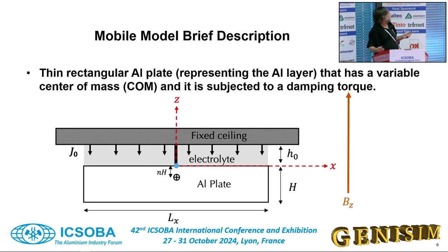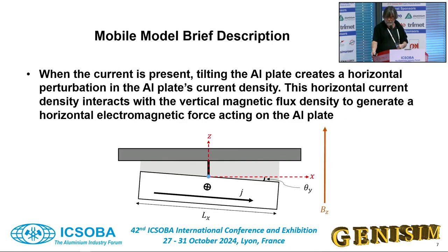If the current density is enough, depending on the ACD and the metal pad and the magnetic field, it will amplify or decay. So you kick it, you get an angle. It's a thick plate, so it can only oscillate in what we call a 1-0 mode or a 0-1 mode in the other direction. Those are the only two modes allowed, because it's a rigid structure. But if you kick in one direction, the current will, like it's happening in a real cell, transfer the motion to the other direction. That's how you get the oscillation.